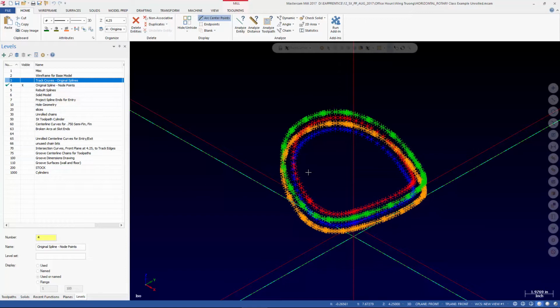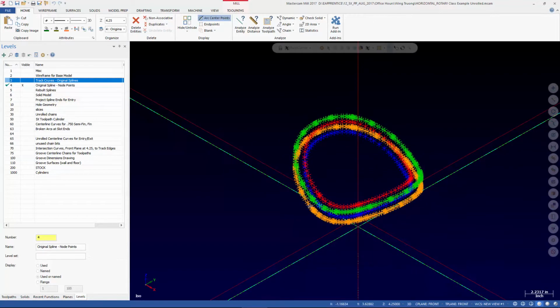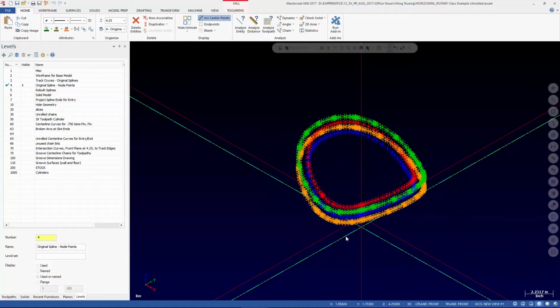You start cutting, and you're like, well, why does it go to 90? Because the alignment of where the cut starts is 90 degrees out of position. Well, okay. So then you ask, why not just let it rotate? Because sometimes the machines don't like that. Sometimes it doesn't matter, and in that case, why not? But again, I like rotating things to where the start point of my geometry matches the 0 position on the machine.